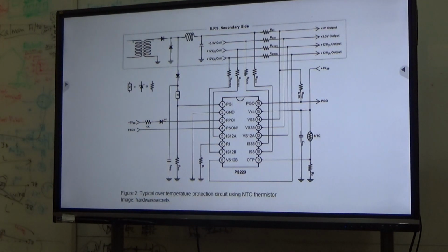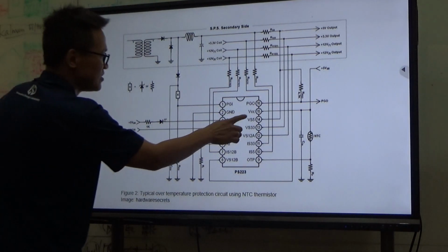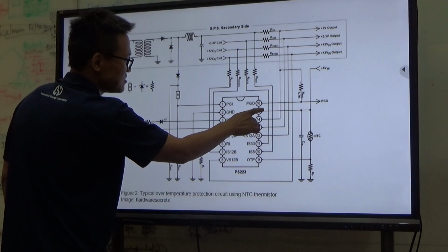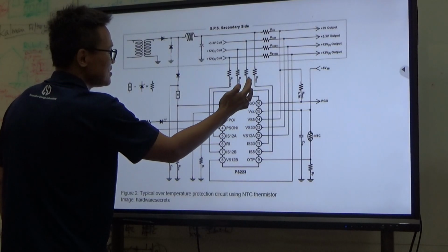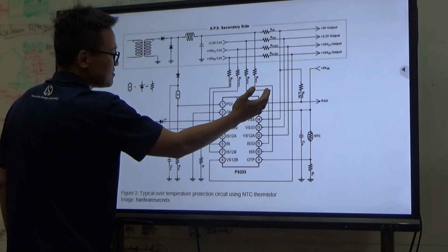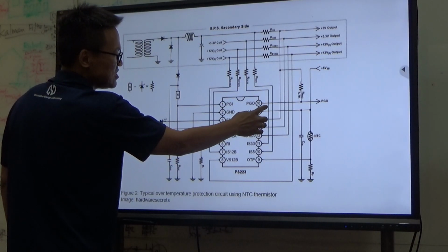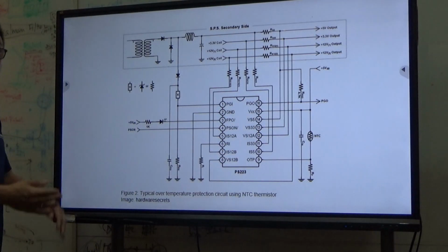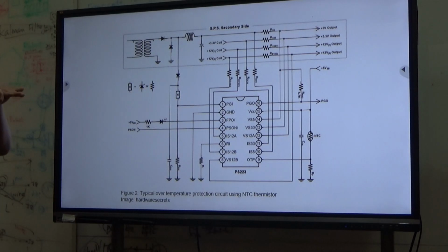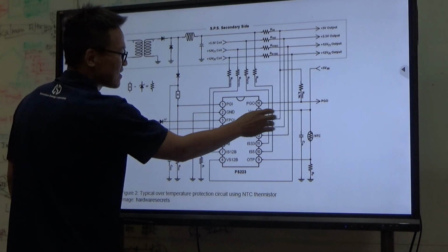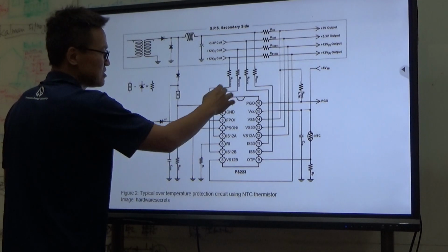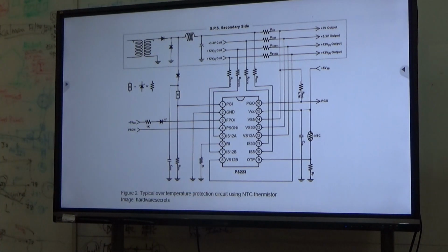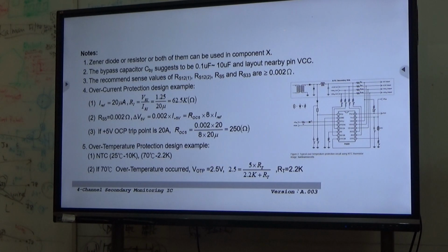Okay? So if I were you, I would put the OTP sensor here. Because when the temperature is higher than the setting point, the VCC is just cut down, so the IC cannot work. But when the temperature goes down and the OTP sensor is still working, then the VCC can be returned back, so the integrated circuit can work normally. Okay? So that is the function.